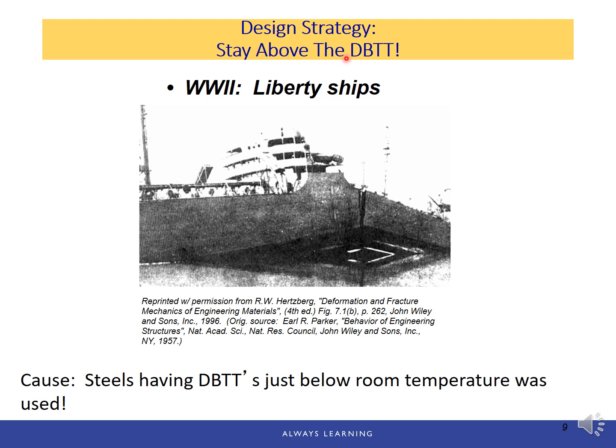So how do we use this ductile to brittle transition temperature? Or where should we use it? Well, structures that are constructed from alloys that exhibit the ductile to brittle transition behavior should be used only above the ductile to brittle transition temperature, because above that temperature, the material is ductile, and below that temperature, the material is brittle. Here is a classic example of this failure that occurred during World War II, when a number of welded transport ships away from combat suddenly split in half.